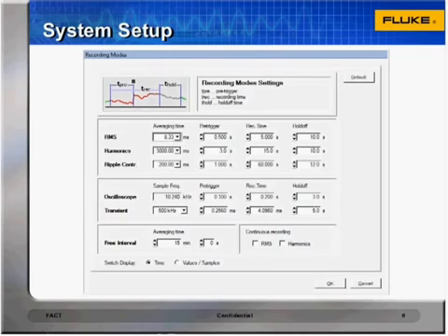Recording modes set some of the timing and sampling levels of the main functions. Some of the important values here would be how long an event should record for, along with the pre-trigger capture. The sampling rate for transients can be lowered to save memory space in an application where 10 megahertz sampling may not be required. Choices for what type of data is captured are also available. For example, when a transient is triggered, would you also like the RMS and waveform graph data stored, or just the high-speed transient view itself?